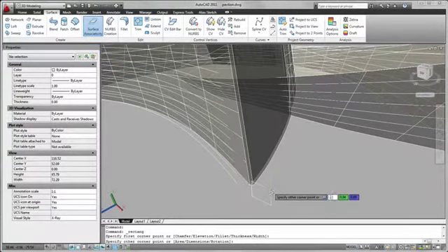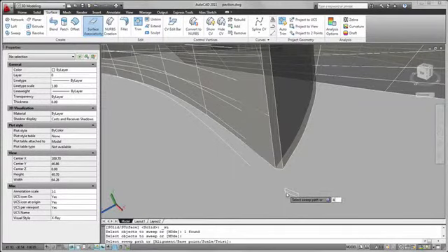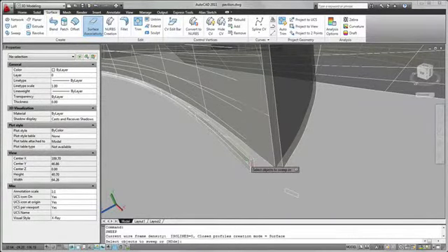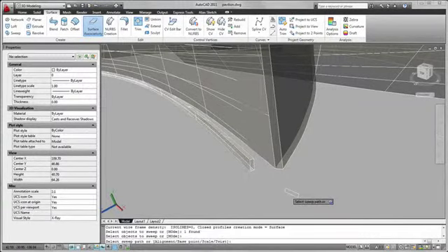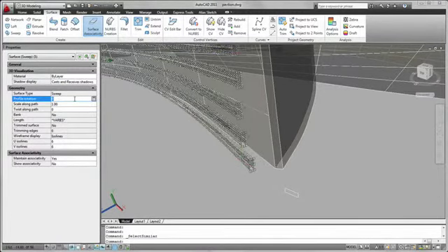I can create a rectangle anywhere in the drawing and then sweep it along the spline paths. AutoCAD 2011 will automatically align and center the profile on the path, or I can select a specific base point. Since this is an explicit surface, I have the flexibility to modify sweep properties such as the scale, twist, or profile rotation, even after the surface has been created.